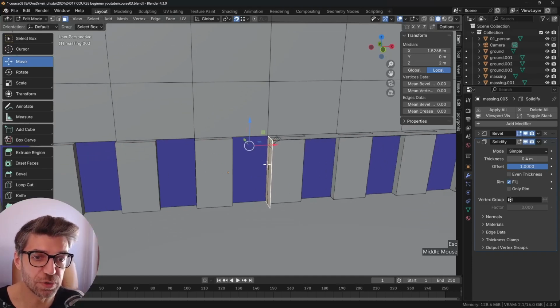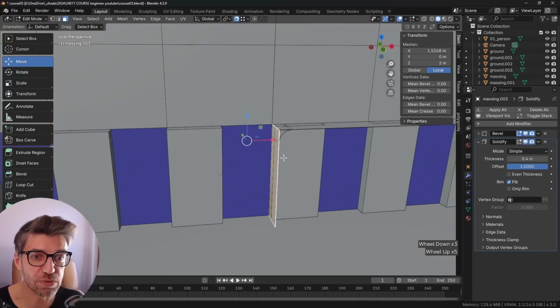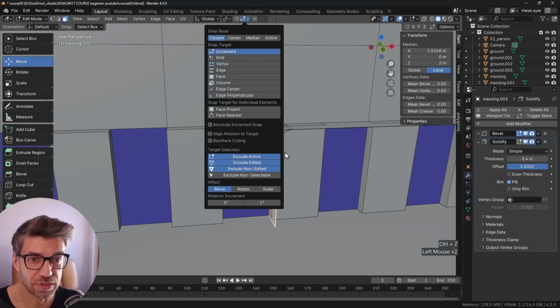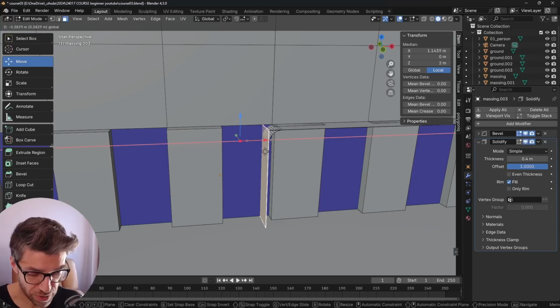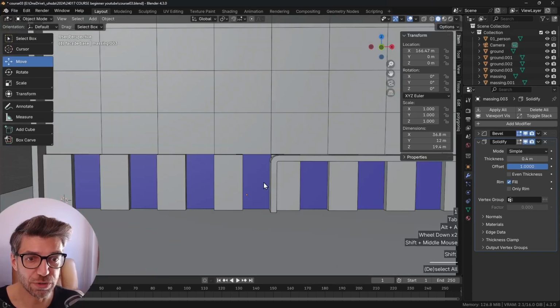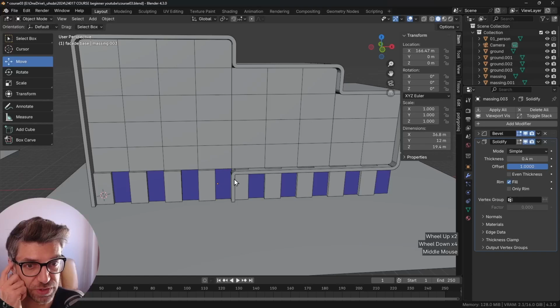The only thing I'm going to do now is with this rounded element that we have here with the solid facade, I'm going to slightly move this inside of this glass. Let's disable the snaps. I'm just going to go to grid by default and move that in the negative direction because the arrow is pointing in that direction, minus 0.1 there. So that's going to have a bit less of an impact of that sort of intersection.